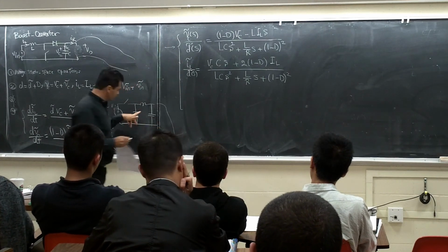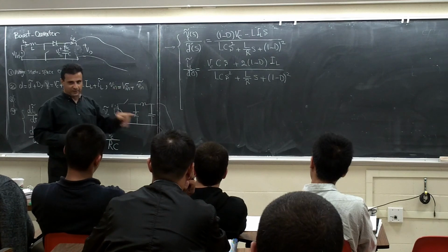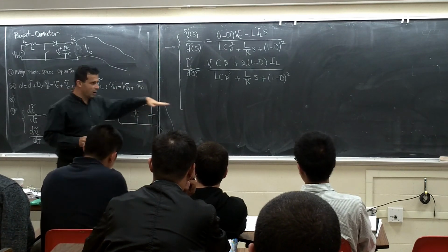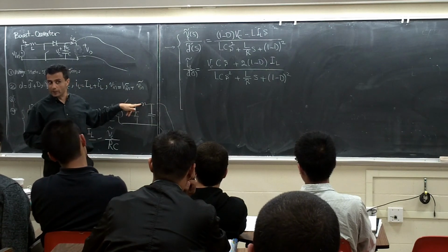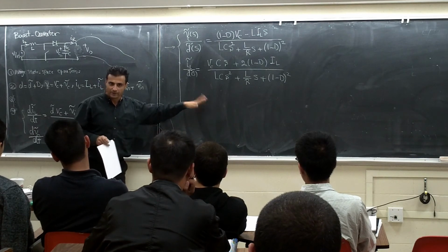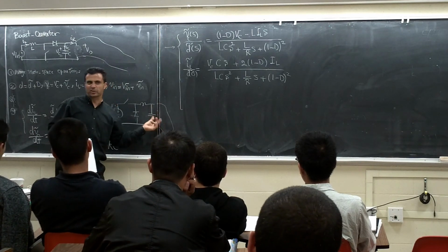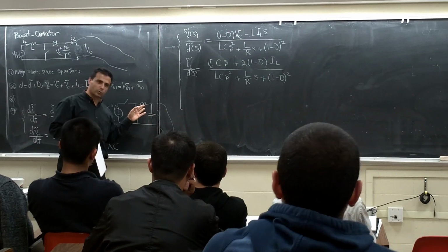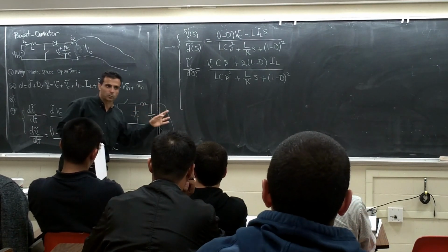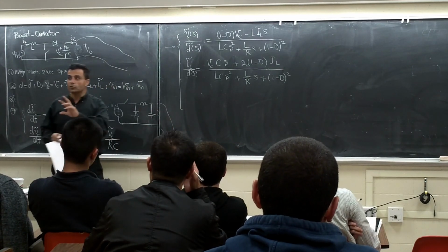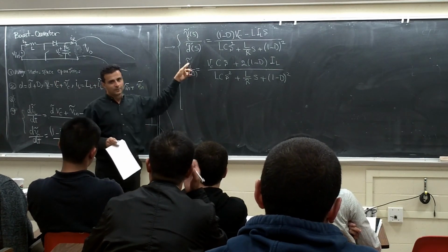Look at it here. In steady state, how much current is going there? Zero, right? Basically, if I can regulate the inductor current, this system is working like a current source, because the current going here is just the ripple current. The average of this one is zero. If I control the average of current here, I'm controlling the average of current here. This is like a current source, right?